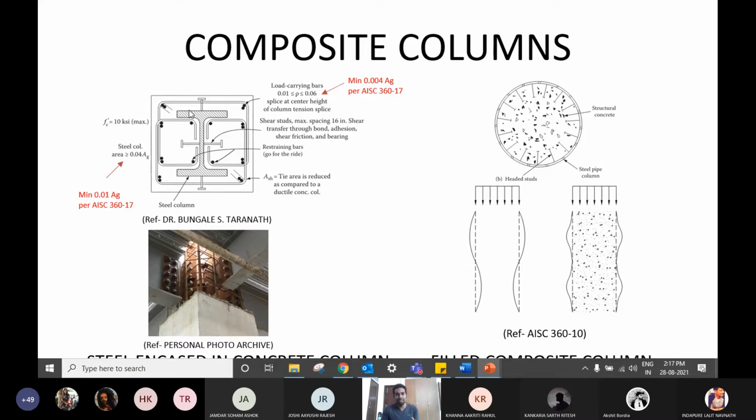okay, better than this design, we go for this design because it is being restrained, right? It's not going to buckle inside the structural steel. Okay, so in most of the cases, the one on the left side is predominantly used, for it's faster with the construction aspects.